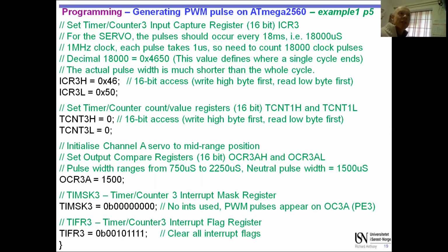It's always good practice to clear the interrupt flags when you set up a device at the end, before the program becomes live. Even though we're saying don't use them here, we don't want any weird effects. If we subsequently enable interrupts later, these interrupt flags could still have an interrupt pending from before we even configured this time, and that would be really dangerous.